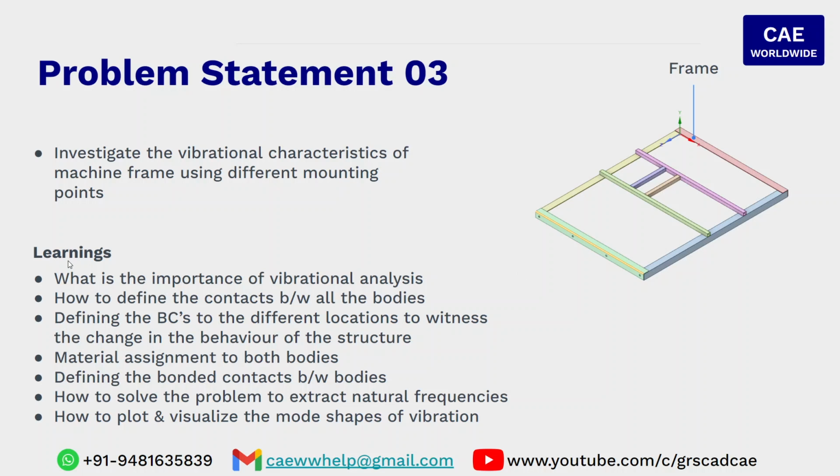The learnings from this problem are the importance of vibrational analysis, and how to define the contact between all the bodies, because there are so many bodies interacting with each other. Next is defining the boundary conditions at different locations to witness the change in the behavior of the structure. As I discussed, the boundary conditions can be applied either to the center 2 holes on either side or the end holes on the other side.